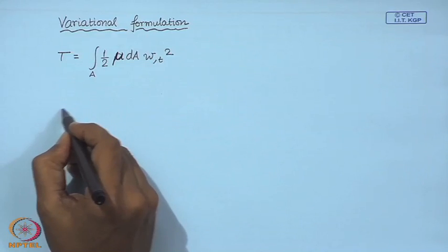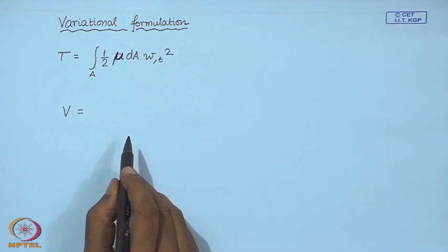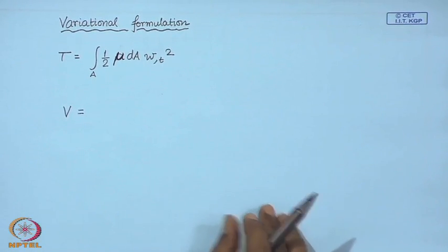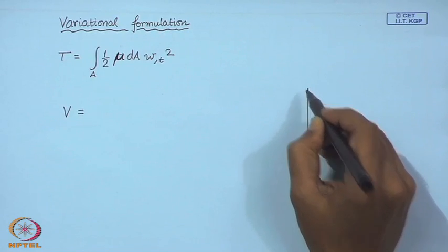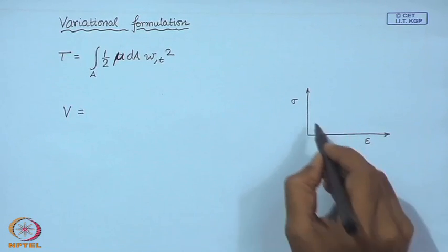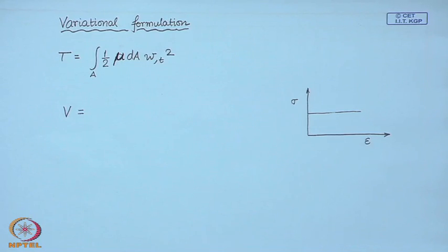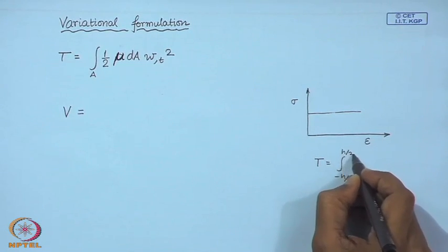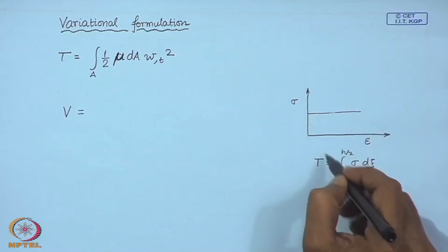Next, we would like to find out the potential energy when the membrane deflects. To determine the potential energy, we have considered that the force per unit length, the tension in the membrane, the stretch in the membrane, remains almost constant, it does not change. If you think about it in this way, the stress in a material remains fixed, only then the force per unit length, which is determined by integrating the stress, must also be constant because T is fixed.